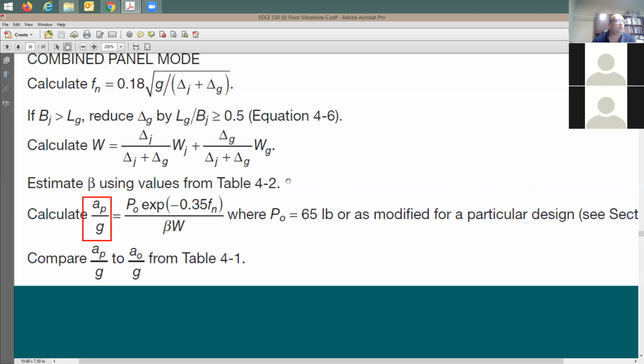So let's say that you have an equipment on the same floor next to this where vibration is going to be happening, right? So you know that there is some acceleration in there. And let's say that acceleration there is going to be maybe about 2-3%, right? Excuse me, like 1/4% or something like this. If this is 1/4%, this gives you the feeling that you don't have the full 0.5% here to consider if you have an office use.